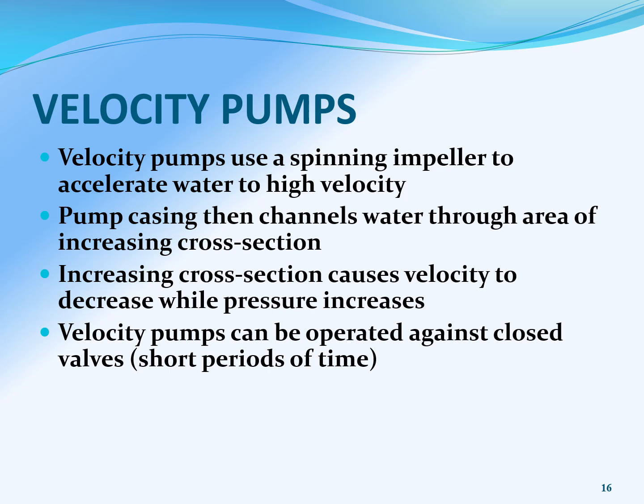One of the other advantages to a velocity pump is that it can be started against a closed valve, right? And that's typically what you need to do. So you have what they call a foot valve or an auxiliary valve right downstream of that pump. As that pump turns on, it pushes against that valve and causes it to slowly open, right? And one of the advantages to that, of course, is you're preventing water hammer.